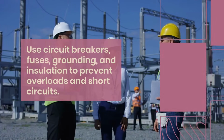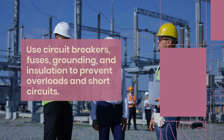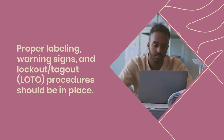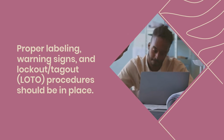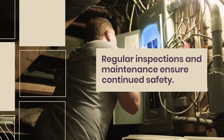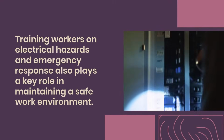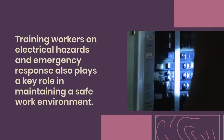Use circuit breakers, fuses, grounding, and insulation to prevent overloads and short circuits. Proper labeling, warning signs, and lockout, tagout, LOTO, procedures should be in place. Regular inspections and maintenance ensure continued safety. Training workers on electrical hazards and emergency response also plays a key role in maintaining a safe work environment.